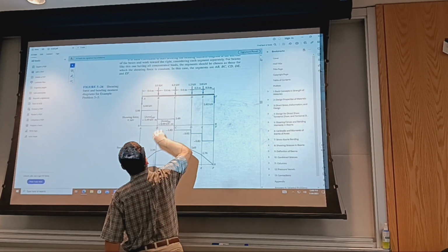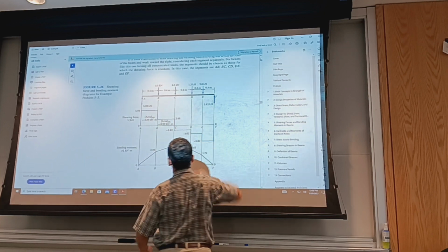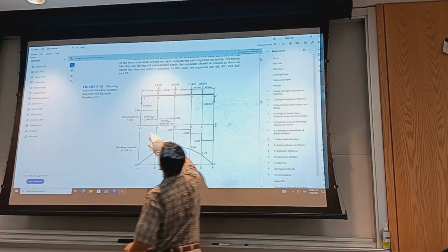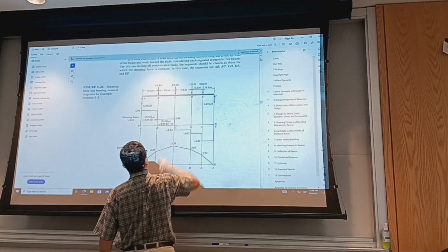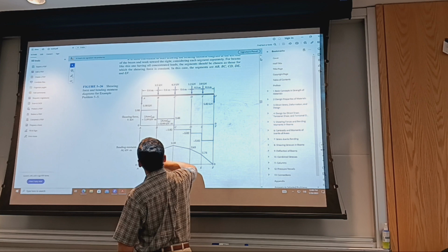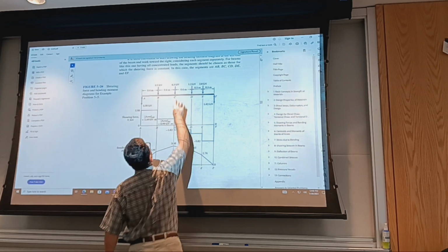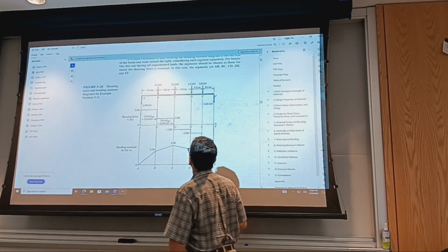Make sure when you draw your diagrams, you of course start with the load diagram and put the reactions, identifying first the reaction forces in your diagrams to be aligned with the load. So things happen at the load, all right?